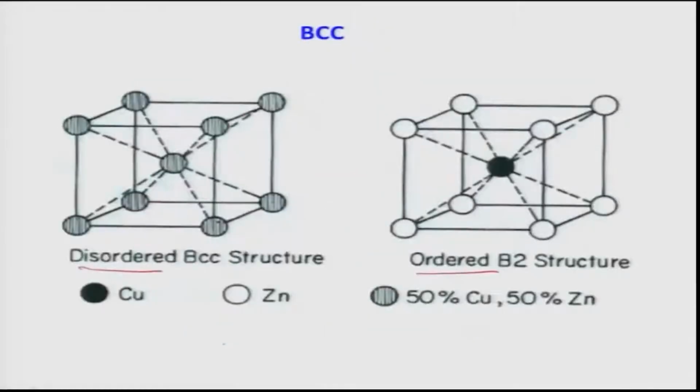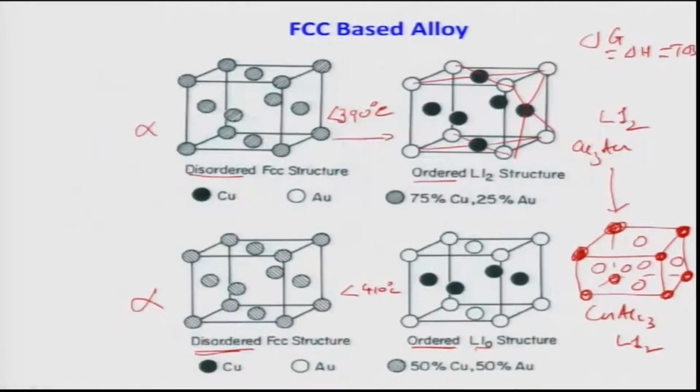Which are the 110 planes here? Let us go back to the crystal structure. So you see, this is one of the 110 planes. If I draw a body-centered displacement, which is along the <111> body diagonal, half <111> displacement means one atom going from here to the central atom.